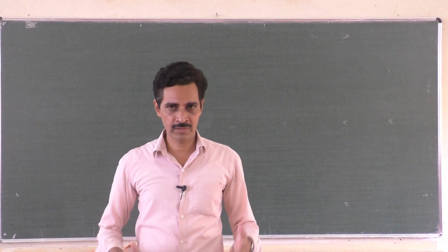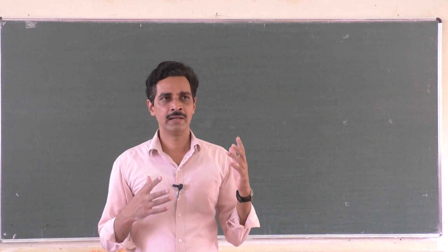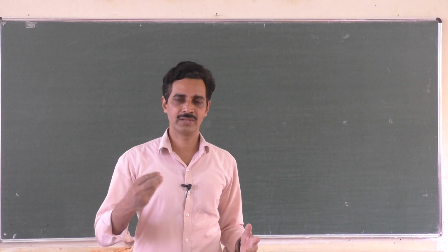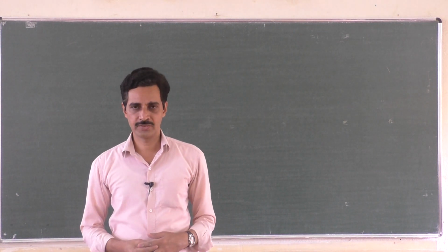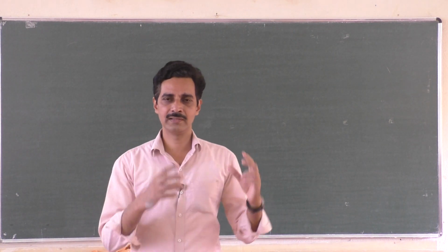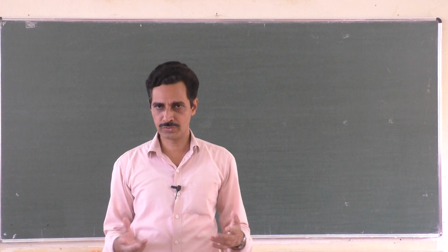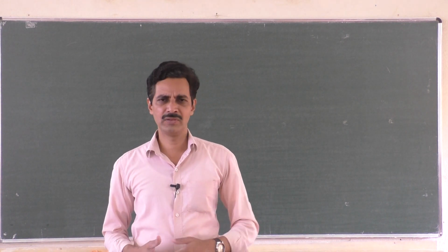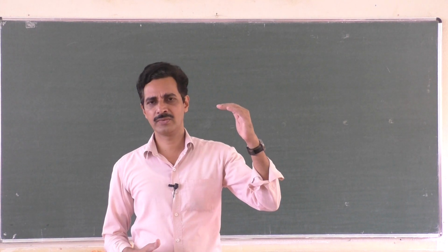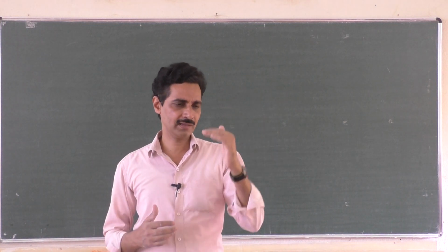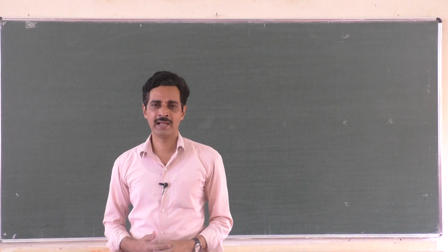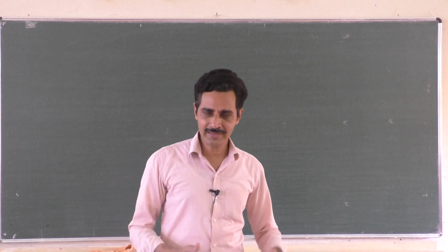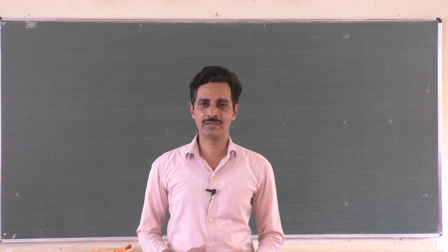resistive circuit. We know that current and voltage in a purely resistive circuit are in phase. Whereas in a purely capacitive circuit, if you take a capacitor and connect it to an AC source, in the beginning current will be leading and at the highest value, and as time passes current decreases and voltage increases. Means current leads the voltage by an angle of pi by 2. We will revise it and then we will move on to another circuit, that is inductive.